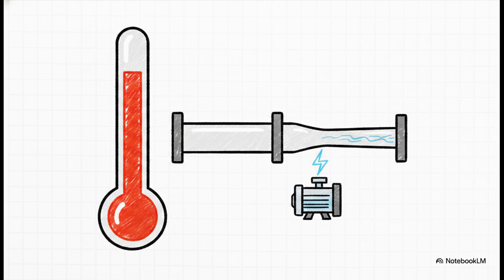The chiller now sees warmer return water and lower evaporator flow. It hits the exact same 500-ton target, but it pulls it off by moving fewer gallons rather than demanding colder water. And as you'd probably guess, because the flow is lower, pump energy drops. This is honestly one of the absolute biggest motivations for designing high delta T systems in the first place.